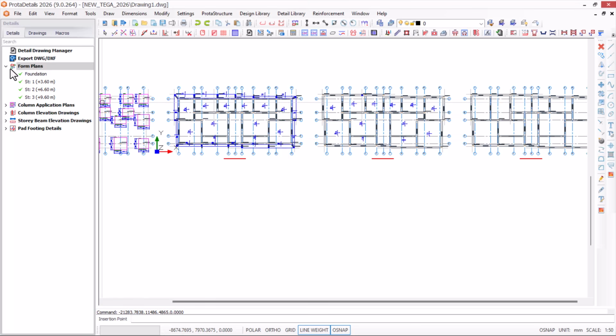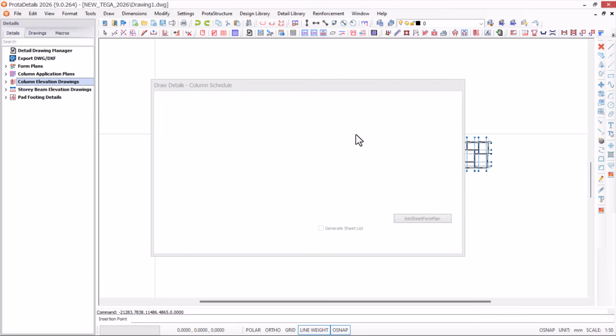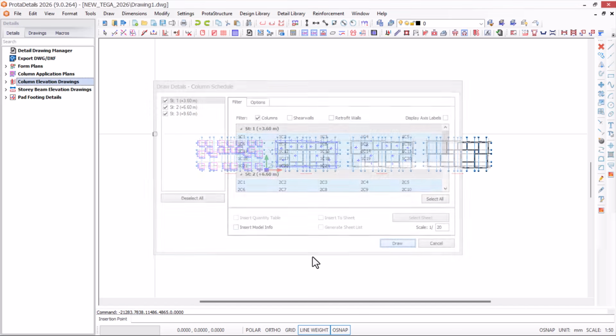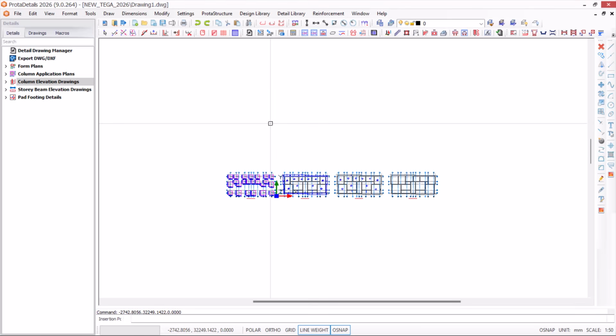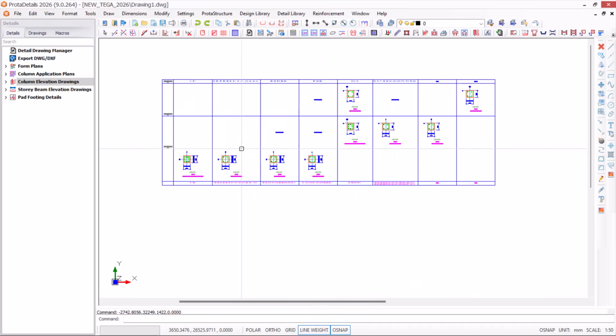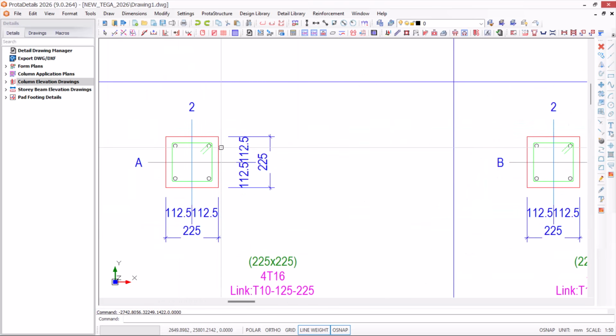Then we go over to the column schedule. I click here and do column schedule. I don't like generating my column sectional drawing because it doesn't draw well, so I use the one from the StoneBridge styling template. I click on this, click up above here, and draw this. Okay, that is fine. It will not detail or generate my column schedule, so I will transfer all the information to the StoneBridge template.